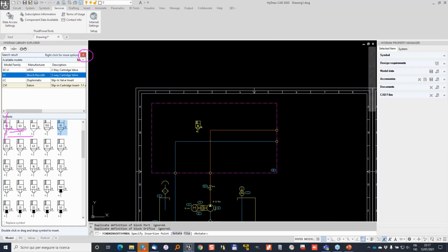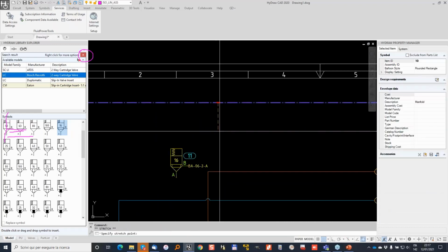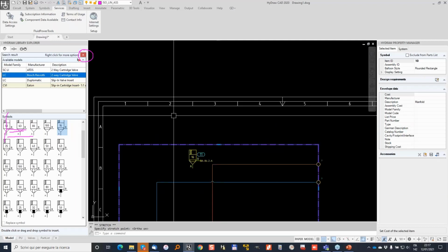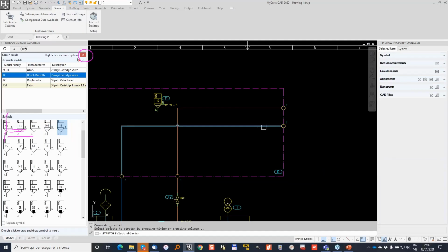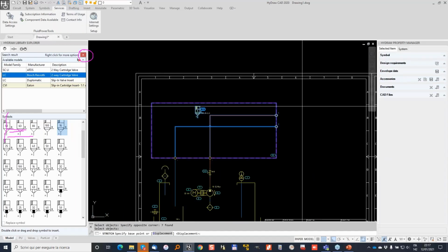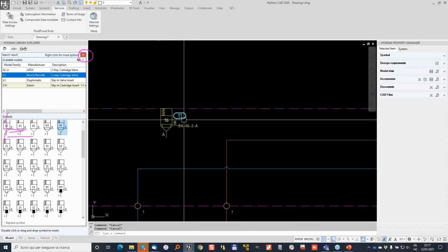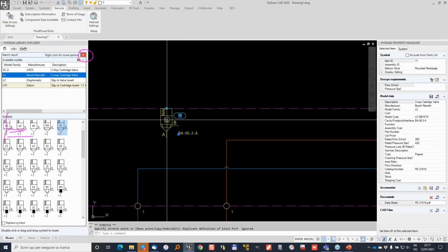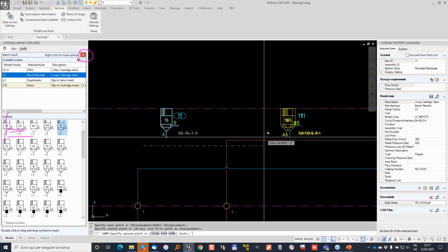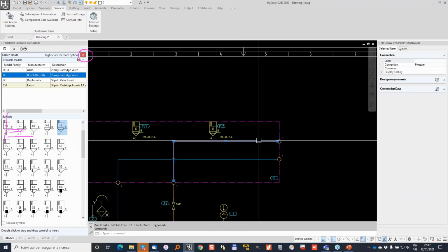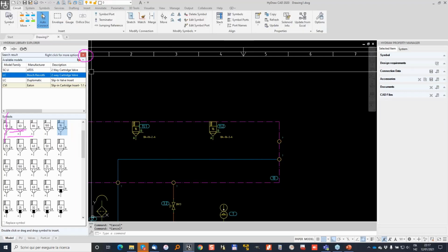Well, let me put it here. I need to make some room, so I'm going to stretch this down, because on top I want to place the sleeping cover. And again, I can use the AutoCAD stretch command to make some room here. And I'm placing this here. Let's say that I need two of these elements, so I can just copy, place it here. And I'm removing this because I need to make a connection, automatic connection.